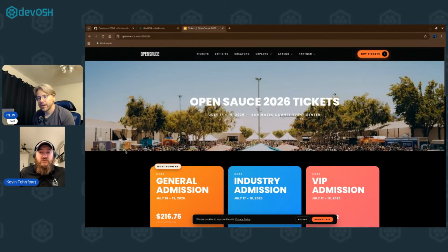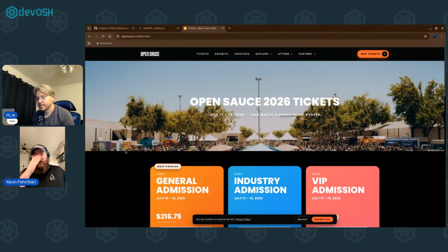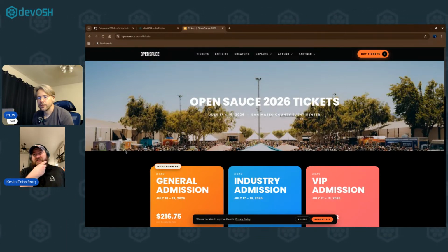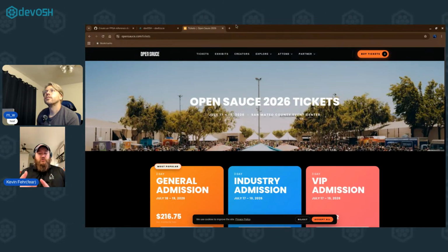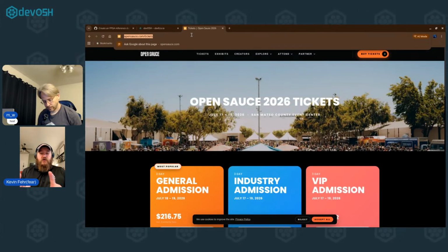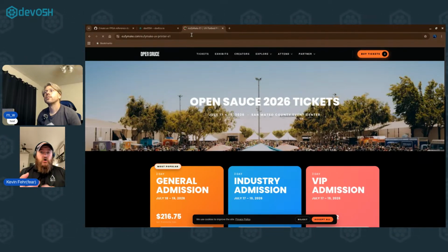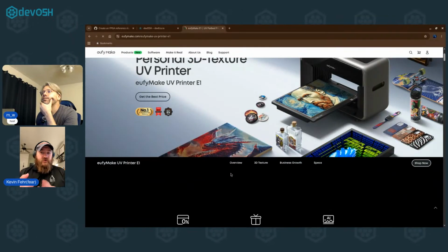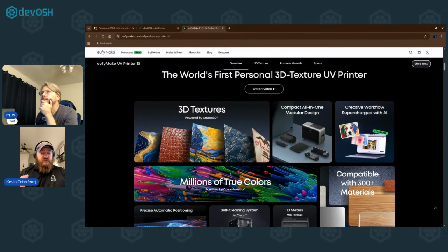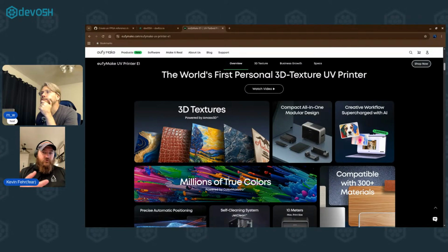Did you find a good way to coat them so they don't scratch real easy? Yeah. I did some more digging, and I found out that there are three ideal ways you can fix this. Number one, have a thicker coat on the UV. Some colors are a lot more brittle than others. So if you do a couple extra layers and a clear coat on top, it provides a little bit more durability.